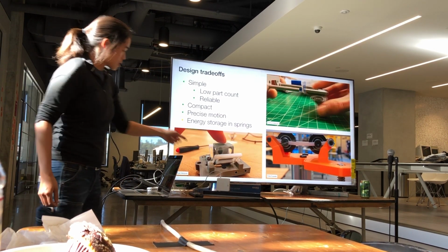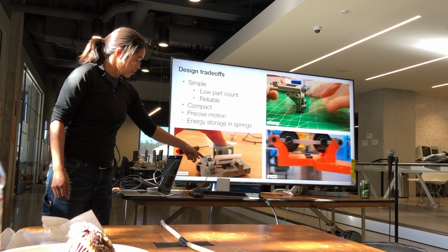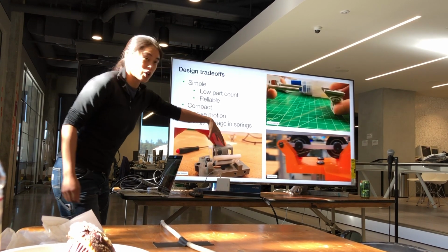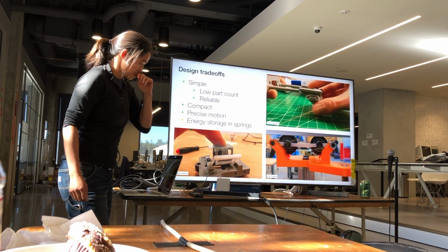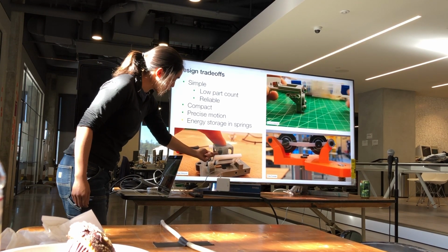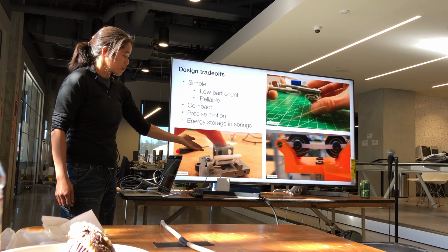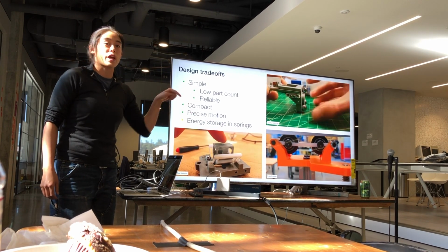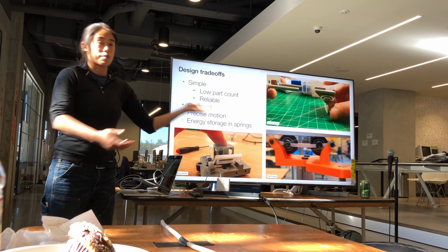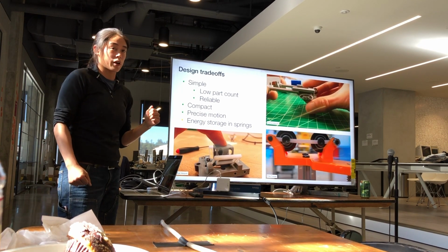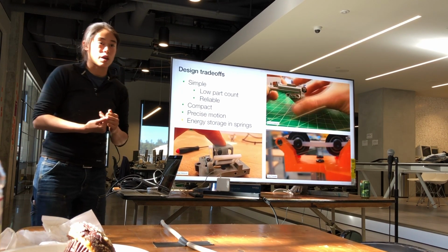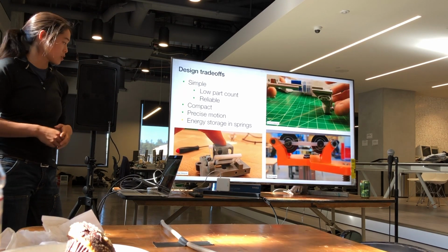And then finally, this is another example from Joshua of a pen holder. Imagine this one turned 90 degrees, and you could put a pen in there. Here you might have it so that the actuator that's pushing the pen down is only actuating in one direction, and then maybe the retract you can just get from a spring, or the spring compensates heavily for the amount of retract force needed.